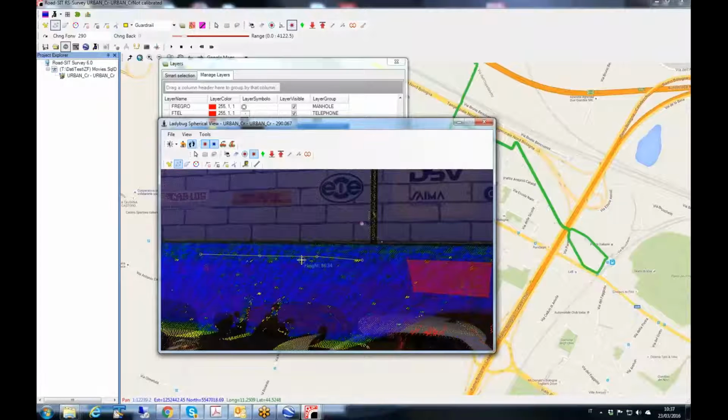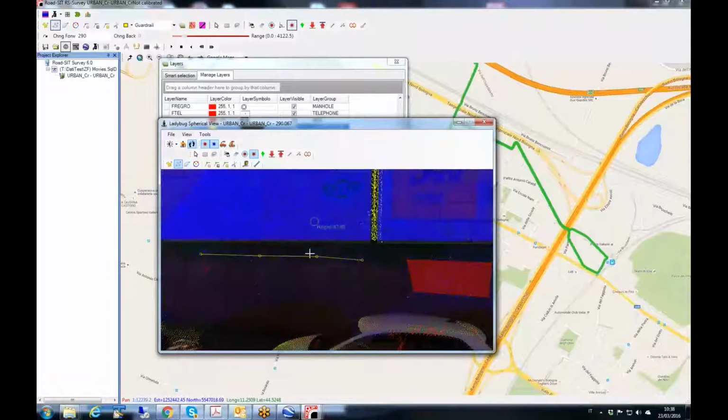You can manage attributes once you finish your drawing. The attributes can be managed directly in AutoCAD. You can take geometries, layers, line type, scale, and everything else by picking points directly in these windows. And if you need to change the hatch type or hatch style, you can change it in AutoCAD as you normally do.